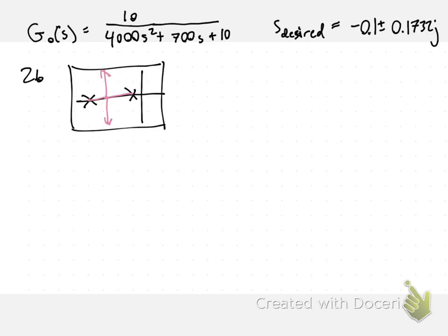And when we look at that, we see that they meet at somewhere before 0.1. And because they meet somewhere before 0.1, using that root locus of MATLAB, we can see that we will never be able to have a zeta omega n of 0.1 or greater, because when we have a pole located somewhere here that's not at 0.1, we'll have another pole that is closer to the origin, causing our tau to be too slow.